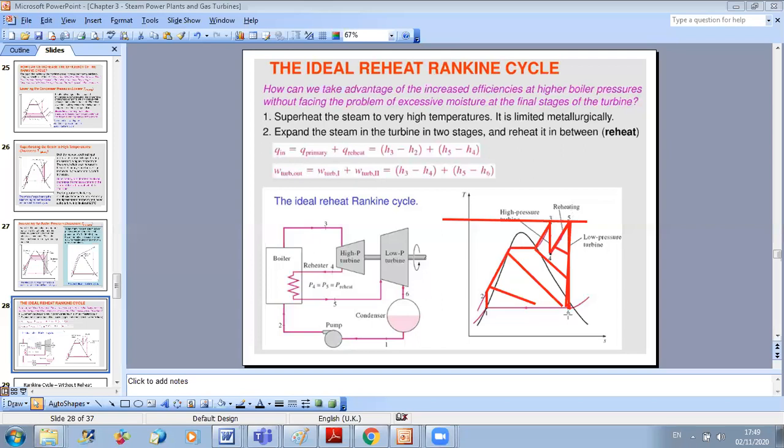Now concerning the total heat that is entering my system, you know that the efficiency is calculated by the work produced, net work if you want, over the total heat that is added, Qin. I will put small q because we computed it per unit of mass flow rate. So it's equal to, the net work here is w turbine 1 plus w turbine 2, and of course for the pump it's minus w pump, because for the pump we are putting work on the system, over qin.